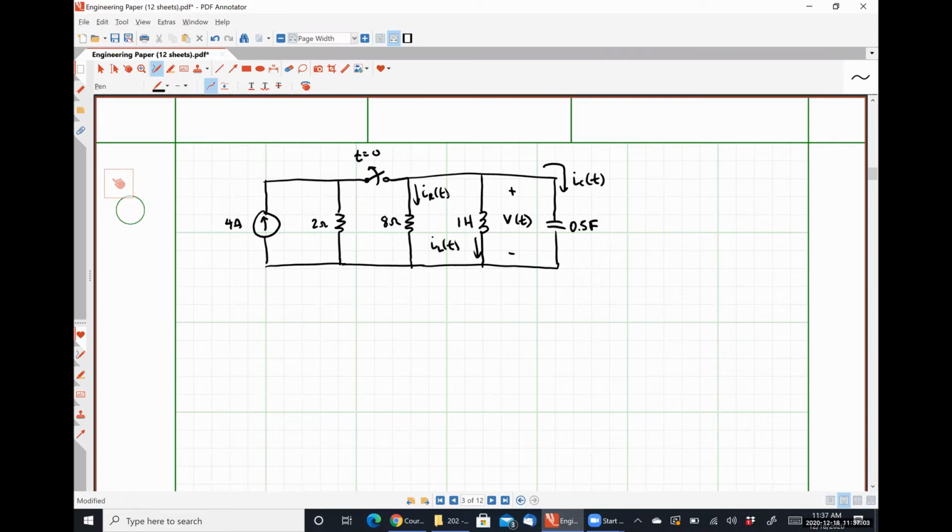For the capacitor, if the voltage is a quantity of interest, the current gives us a relationship that involves the voltage that also involves the derivative. So we have two equations involving voltage and current in a capacitor, and we have two initial conditions that we can take care of. Same for the inductor. But for the resistors, since they can't store energy, we don't really have an initial condition that's stable to be able to deal with.